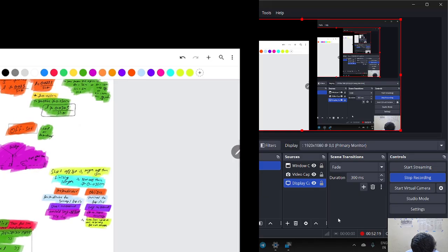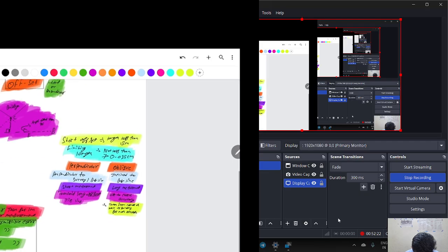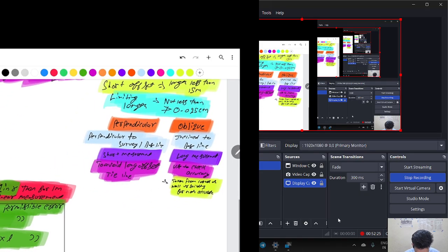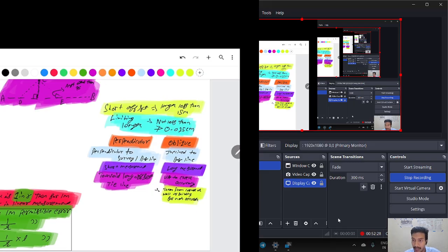Shortening and lengthening perpendicular, oblique. Now this is also most important. Note: if the accuracy of survey work is 1 in R, then for 1 meter, what is the length of the offset error in linear measurement? We have to find the error in the linear measurement, which means error per meter is equal to 1 upon R.